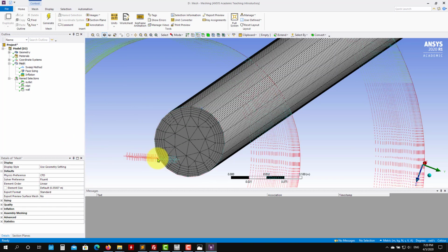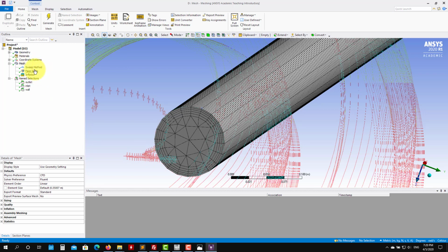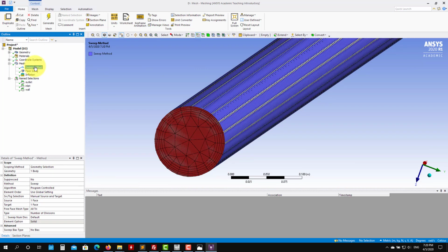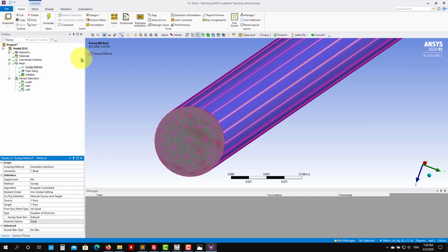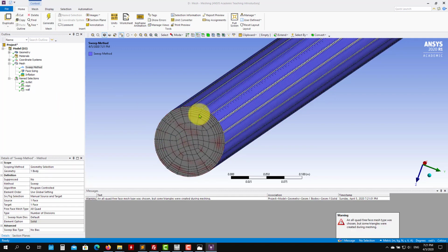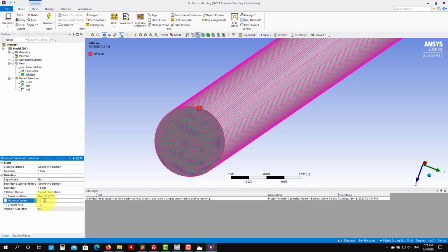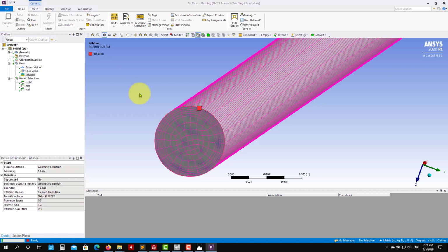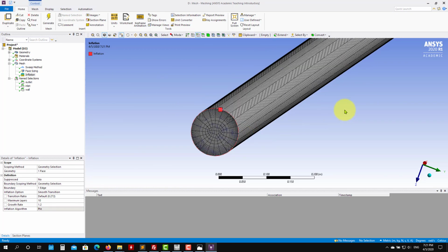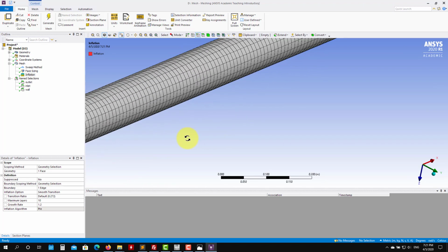Okay, see that we have it now. So it wasn't this slip there. Always remember to choose your physics. According to what you are doing, you will have different meshing requirements and default actions. So let's put here, for instance, all quad, generate, and you see with quads and inflation, for instance, I put 10 layers. Probably this one will give me an error as well. Probably it will be too small here. Let's see. Okay, let's use this mesh, which is not the nicest one, but it's okay.